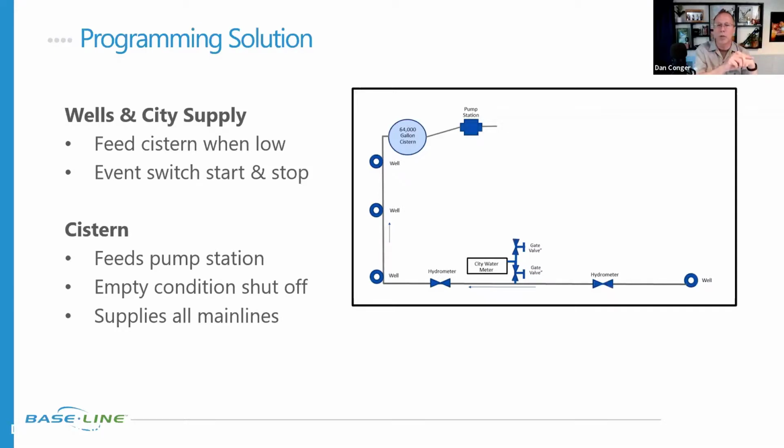And we're just saying the switch is open, switch is closed. That's it. Right. So the actual tool, though, is the pressure device, but it's going through someone else's system. And when we use our pressure transducer, we can see the actual inches in the tank and measure it that way, which is, to me, a little better for my users, because they can see through our system what the level is of their cistern.